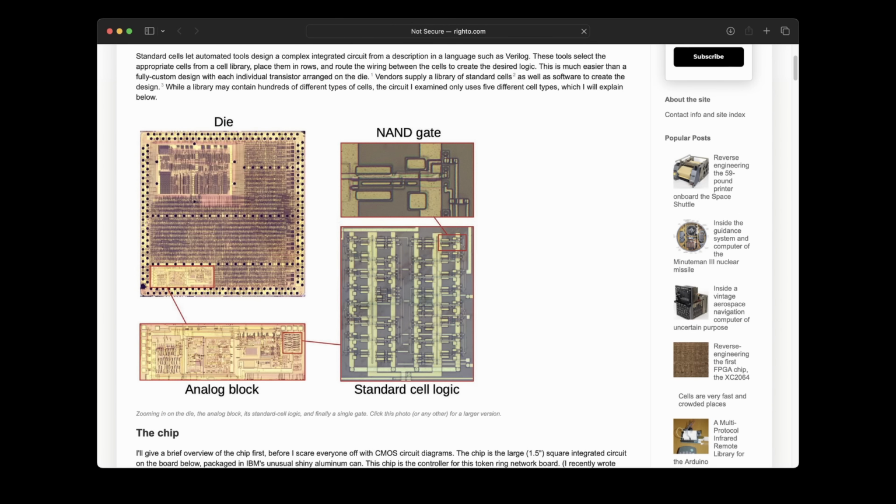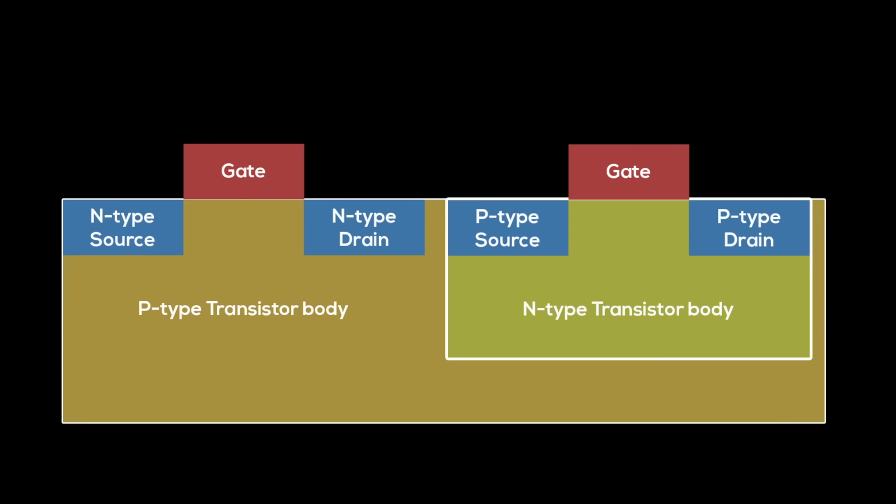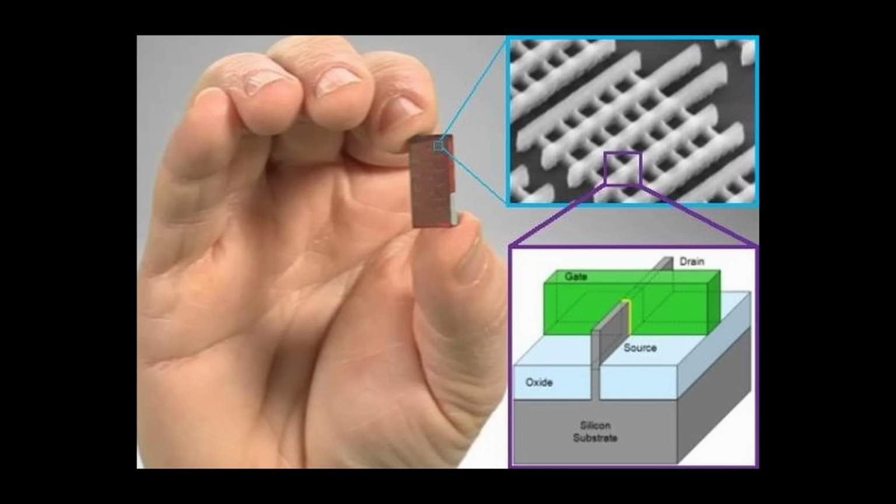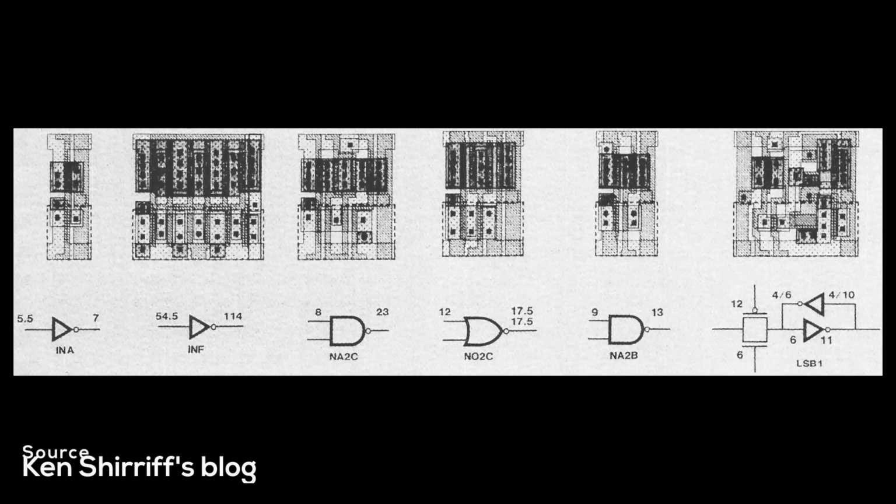With chip design, it's all about efficiency. You start with the smallest parts, transistors, and build up from there. Transistors are used to create standard cells, which go into rows, which build the logic blocks. And many logic blocks combined create a chip. Actually pretty simple if you look at it that way. Now we have all the ingredients. We know that CMOS transistors are a combination of N and PMOS, that current gen transistors are built with elevated 3D fins, and that these transistors are then used to design various types of standard cells, which are placed in neat little rows. And the standard cell is exactly where fin depopulation is starting to work its magic.